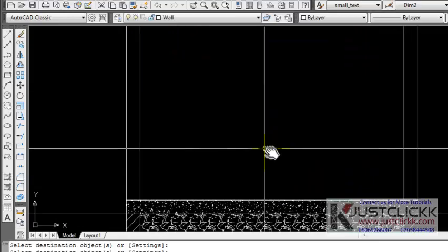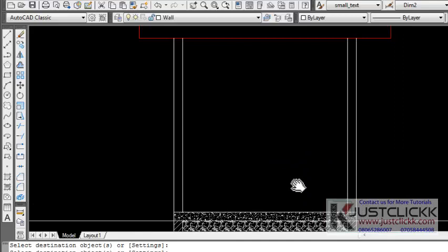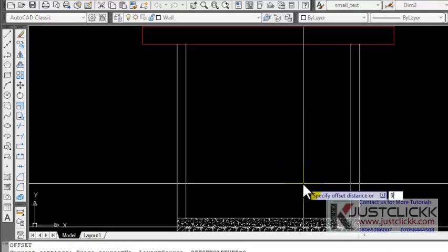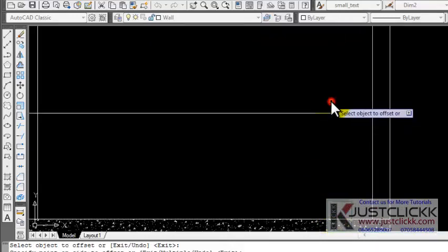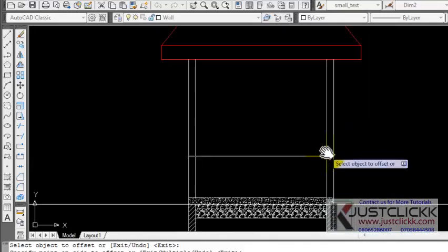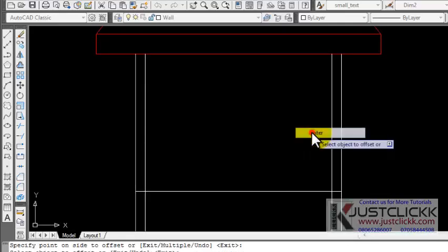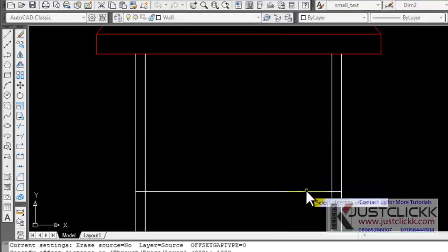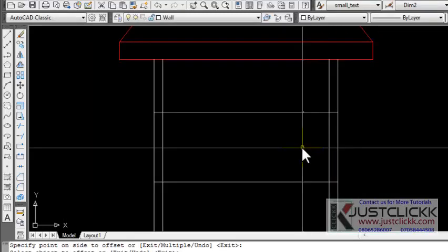So in the walling aspect of this tutorial, let's see how we can accomplish this. Offset 900 from the slab level, which is this. That's where the window is going to sit, the level of your window, the base point of your window. And offset again 1200, which is going to be the height of your window.